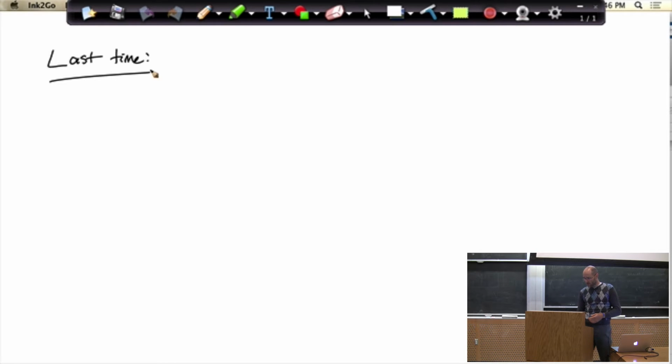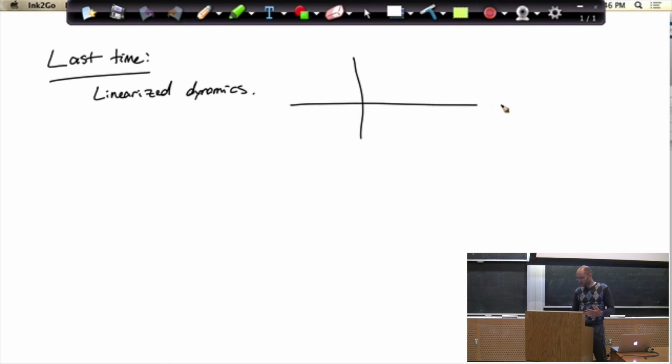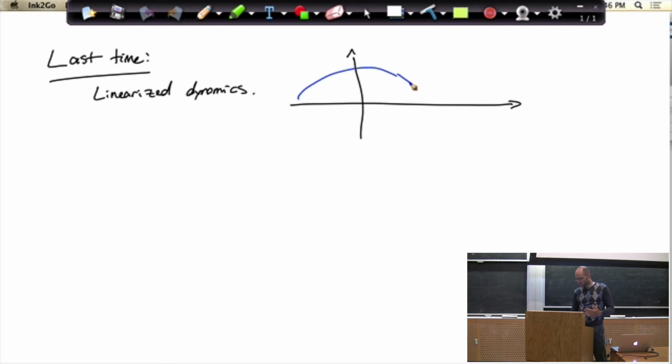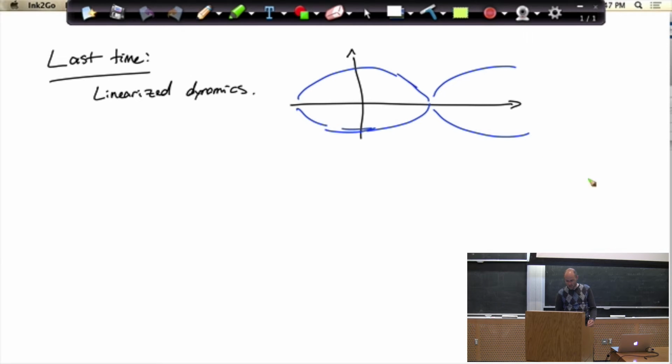We did a little better, I think, using the linearized dynamics around some operating points. So for balancing the Cartpole or the Acrobot on the top, we were able to come up with pretty good approximations. If you remember, I tried to argue that the pendulum dynamics, which looks, in this characteristic form, very, very nonlinear, we were actually getting a pretty good approximation of it with our linear approximation, which captured the nonlinear dynamics in some vicinity, right?